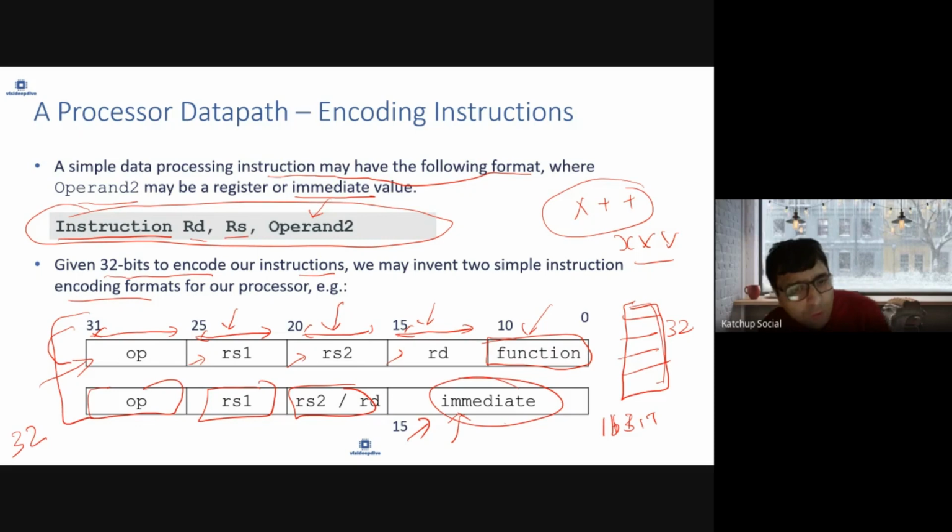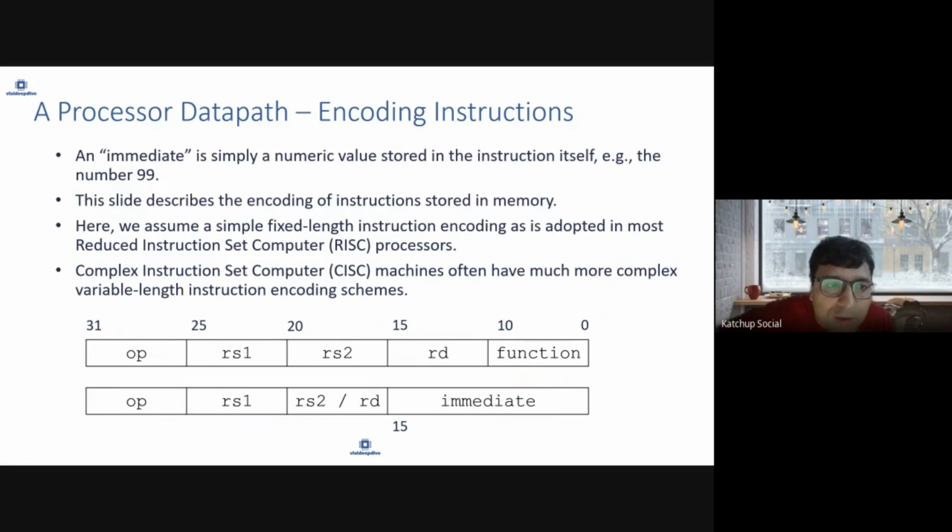So these are two ways we can encode our instructions. Encoding is nothing but saying, okay, maybe for add my code is 00, and let's say add on address 0, then the other address is 1, and store in address 2. This is just giving information to the CPU that you read one operand from this address, another operand from another address, and then add because the operation is add. So don't get confused about it. This is very basic. This is how you can create an instruction set, which will convert into this code and go to the CPU. Let's design this part of it a little bit later.